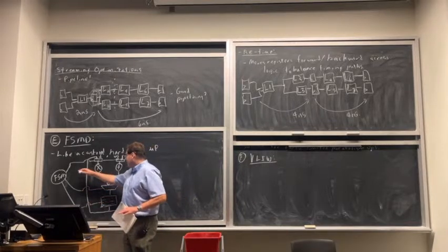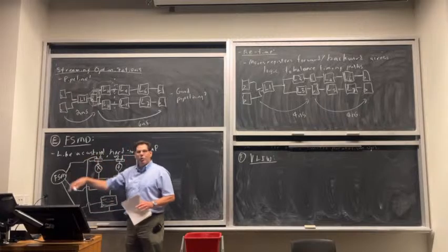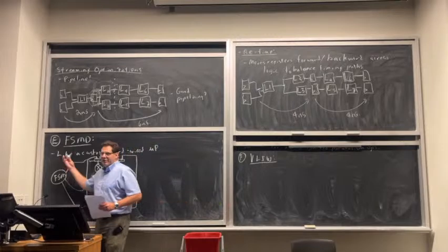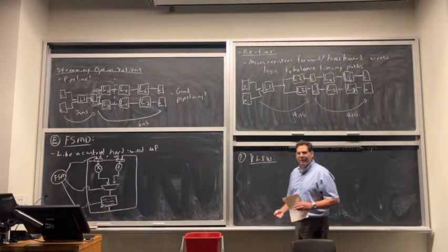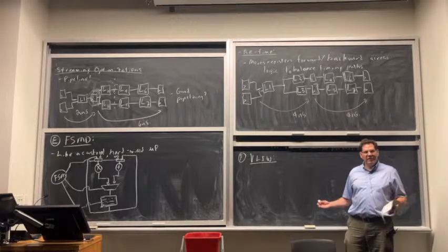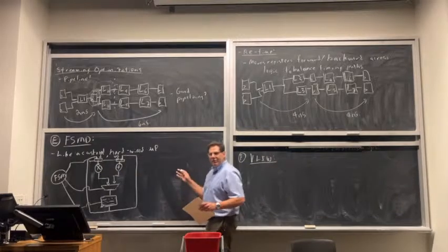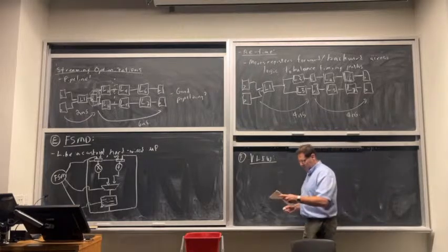So you can imagine just taking this data path, where we've exposed all the control of the data path, and instead of controlling it with a finite state machine, we just said, well, that's directly controlled by the instruction stream. That's a form of VLIW. So it's not the only one, but that basically allows you to transform this to a custom processor model, where you actually have an instruction stream.